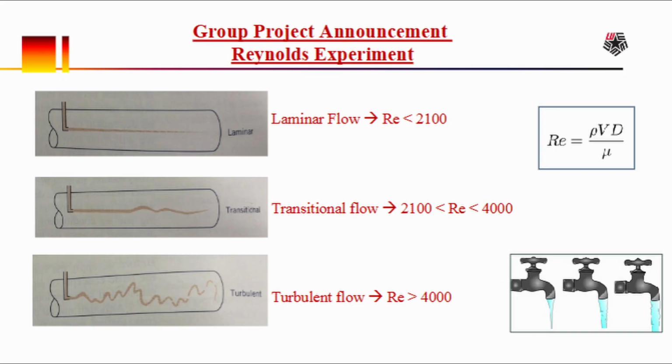The Reynolds numbers for each flow that we calculated were used to compare the observed flow to the theoretical expected flow. Here you can see that anything under 2100 is laminar, anything over 4000 is turbulent, and anything in between will be transitional flow. The observed dye behavior was, for the most part, consistent with these classifications, showing smoother flow at lower Reynolds numbers and increasing mixing at increasing Reynolds numbers.